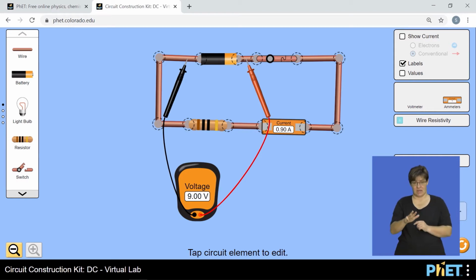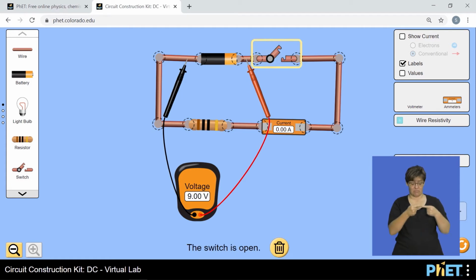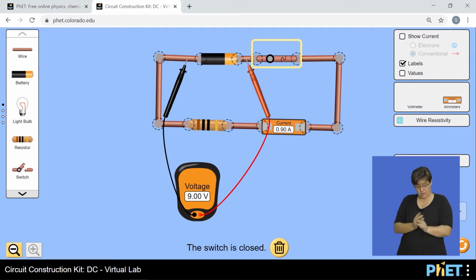But this is only possible if the circuit is complete. If we decide to break the circuit, there's a potential difference of 9 volts, which is actually the EMF, which is also equal to the terminal potential difference. What does that tell us? It tells us that this battery does not offer any resistance in the circuit. So if we have the current reading and the terminal potential difference reading, we are able to determine the total resistance in this circuit.